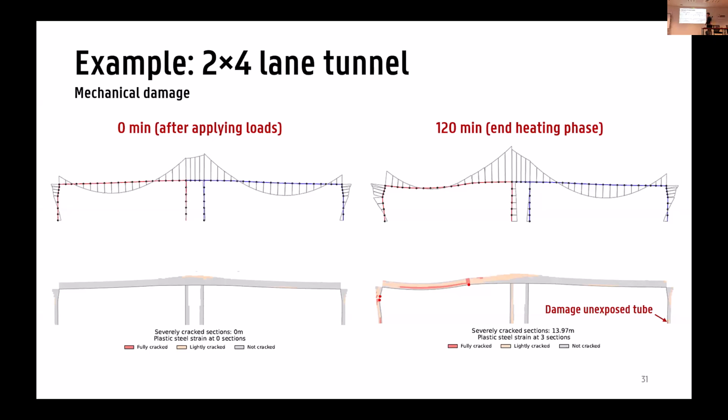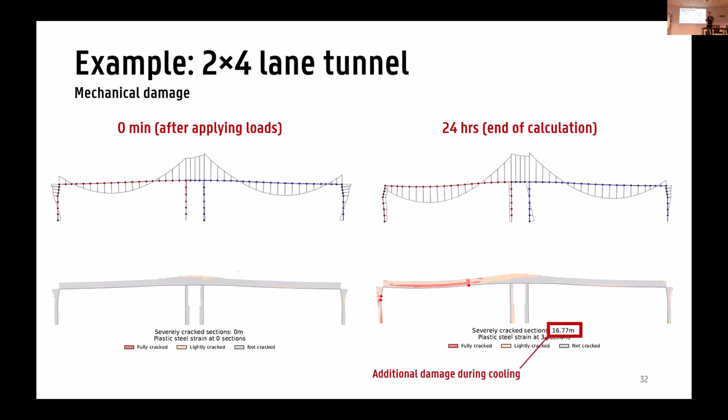If we then also look at the graph at the bottom, you can see where we sum up the total length of sections which are cracked. In this case, after 2 hours, it's almost 40 meters. And if we then take the next slide, which is the damage after 24 hours of calculation, so at the end of the calculation, we see that this is still increasing. So during the cooling phase of the fire, we get some additional damage forming in the structure.